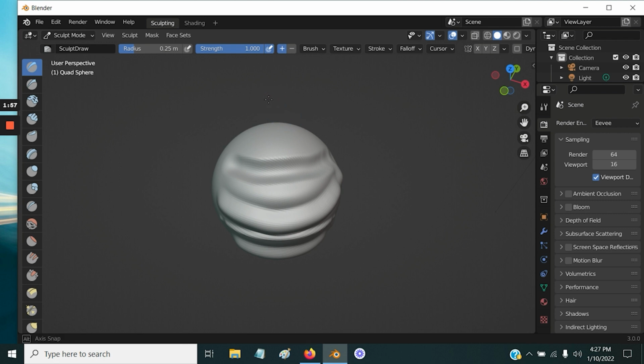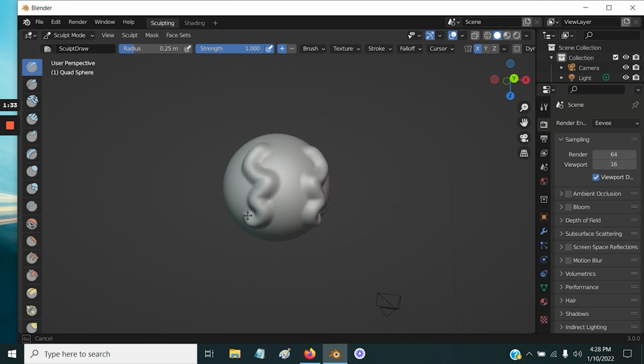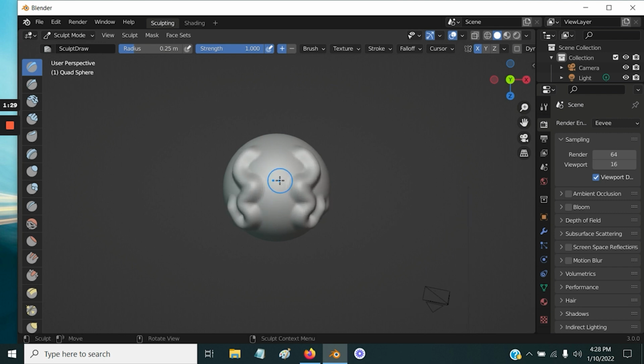And one last thing I would like to discuss before getting into the menus is axis symmetry. Over by the menus, you'll notice we've got this X, Y, and Z next to a little picture of a butterfly. If I go ahead and click on X, now whenever I start drawing, I'm going to get symmetry across the X axis. So if I start drawing, you'll see I get 2 lines instead of just 1.